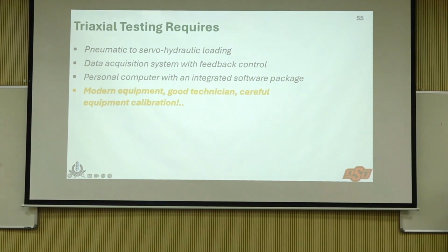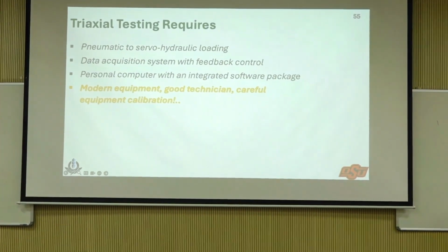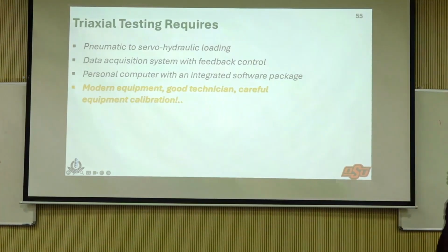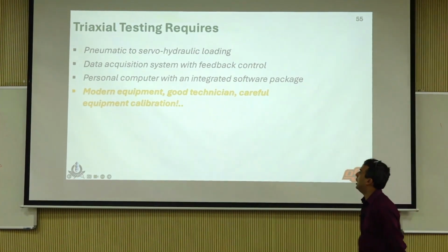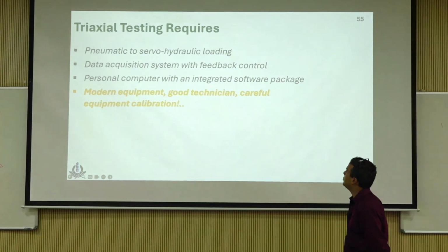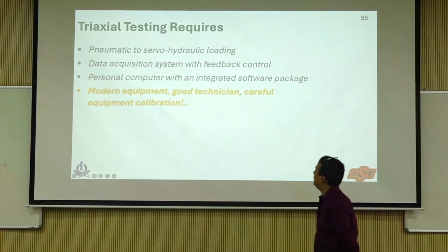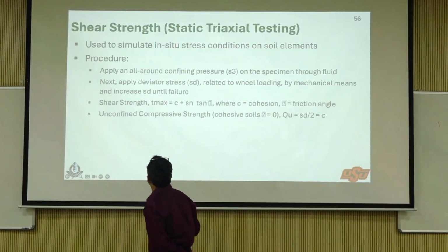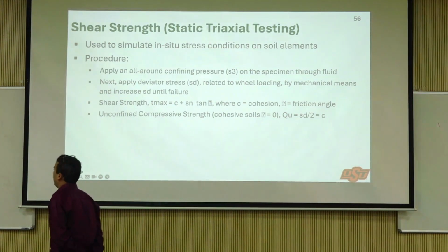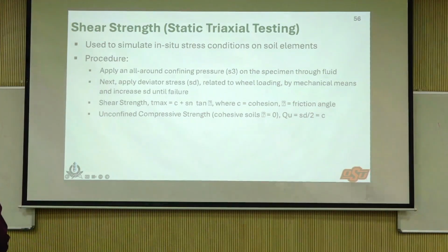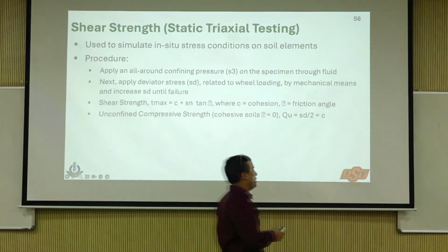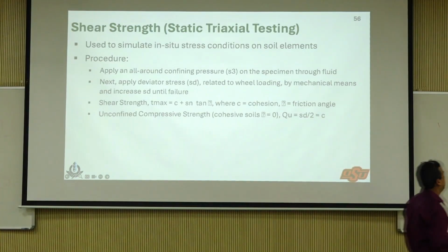Very recently, there is another loading system called electric based systems that I don't know that much about, but I have seen those. And we have the feedback control, and we are going to simulate in situ stress conditions on soil elements.